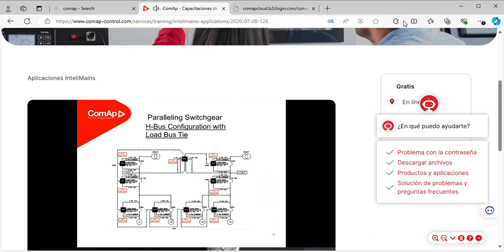This is another example of a system which you saw. Suppose there are multiple utilities coming in, so you can have InteliMains controllers to take care of individual MCBs. Or if you want further isolation to operate as an individual bus tiebreaker controller, you can put in another BTB here, another MCB here, and another BTB here. But you can also consider just one InteliMains to control it as MCB and MGCB operation.